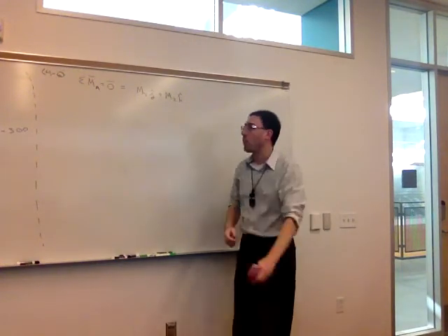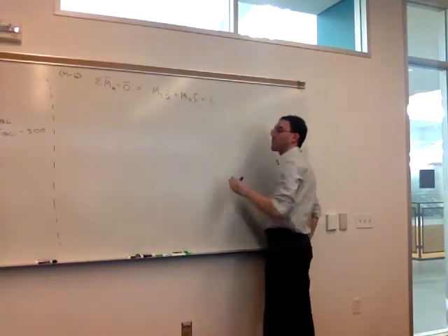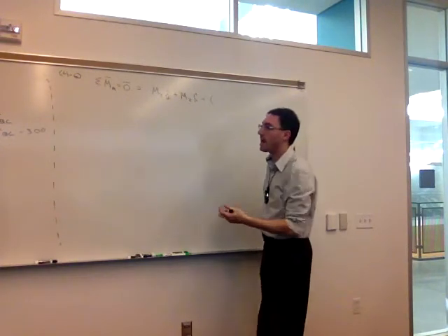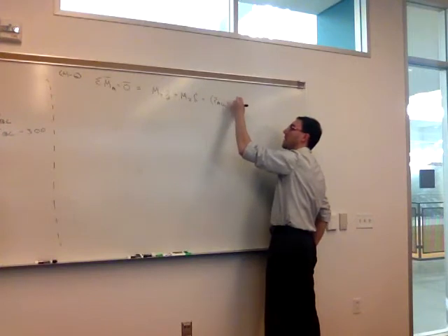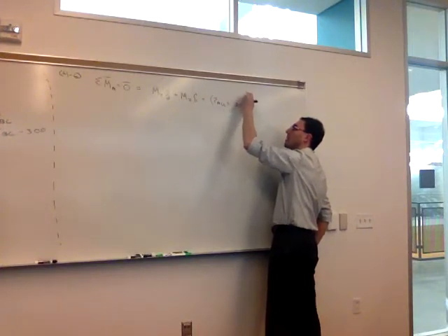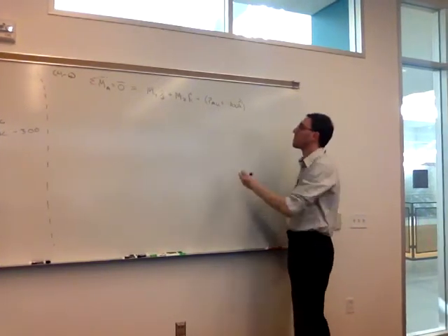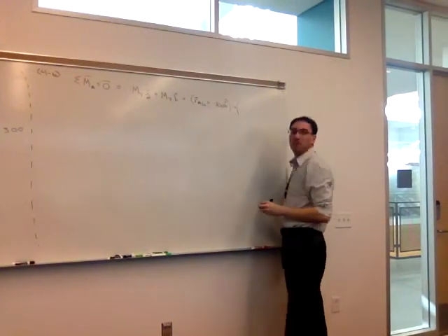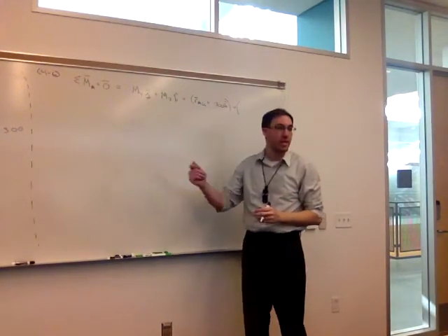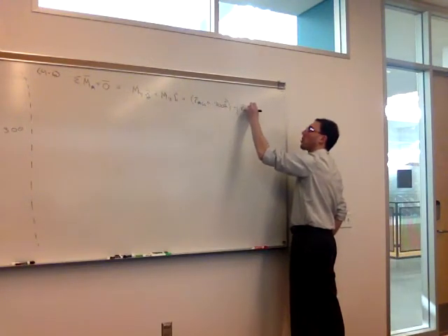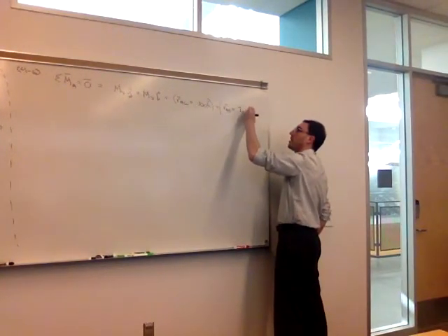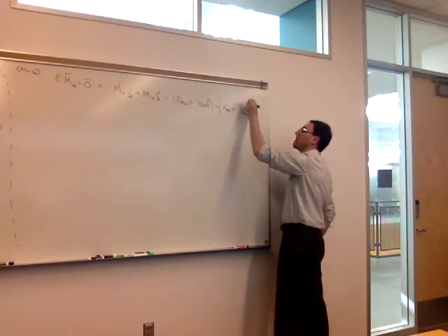Right, now we're ready for the weight. So the weight force will contribute to the moment around A. So that will be RAG cross negative 300 k. And then we'll also have a moment due to the tension in the cable. So that will be RAB cross TBC, vector TBC.